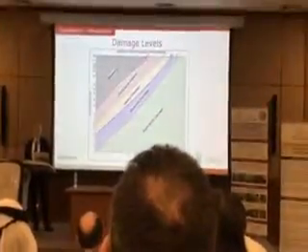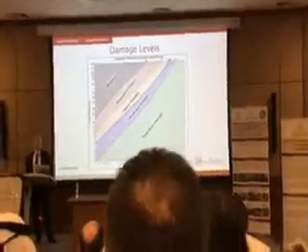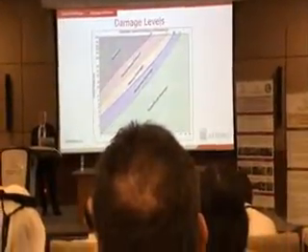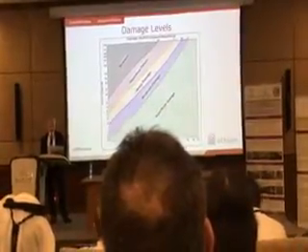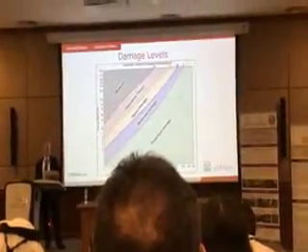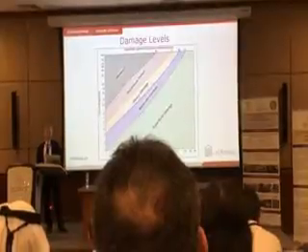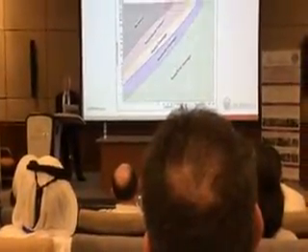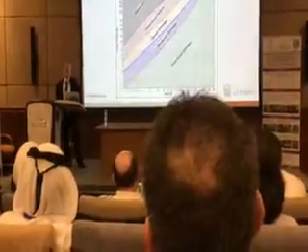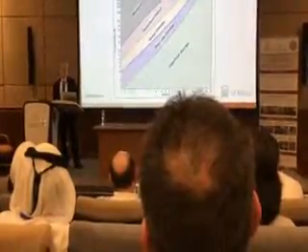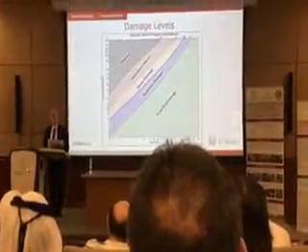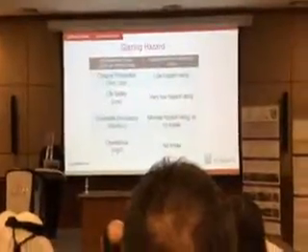And once again, if you have, let's say, 150 kilograms of bomb at 3 meters, it's hazardous failure, right? If it goes up to, say, 10 meters, 30 feet, it's on the border of heavy damage and moderate. So these charts are also available, or you can develop them if you use them very frequently.